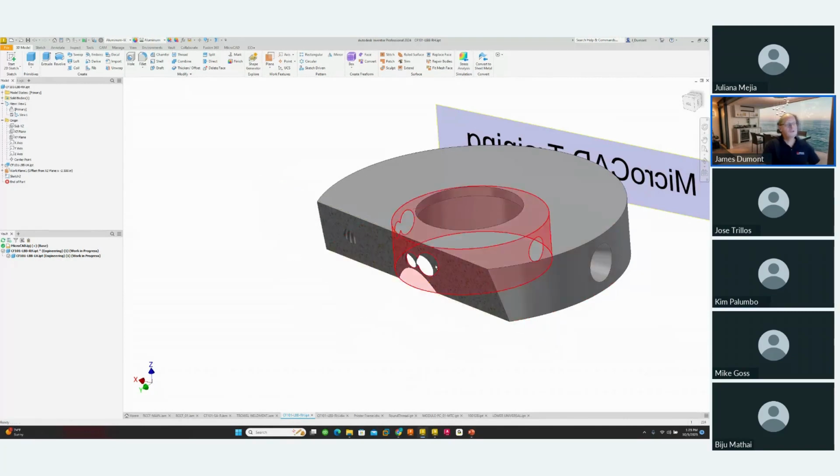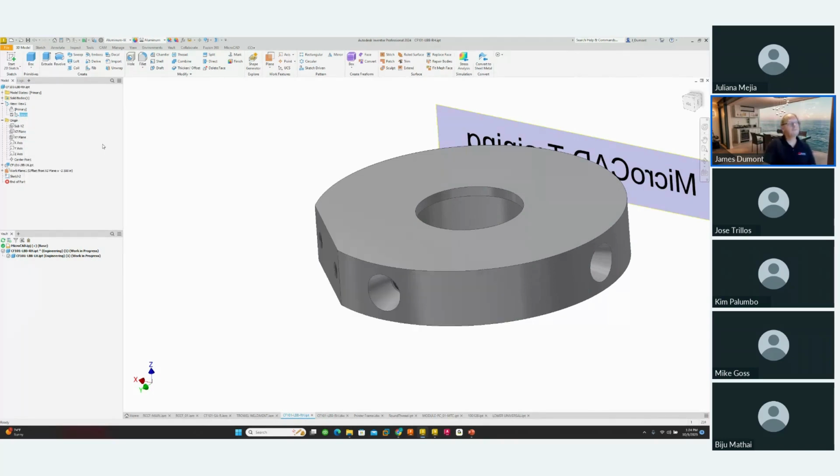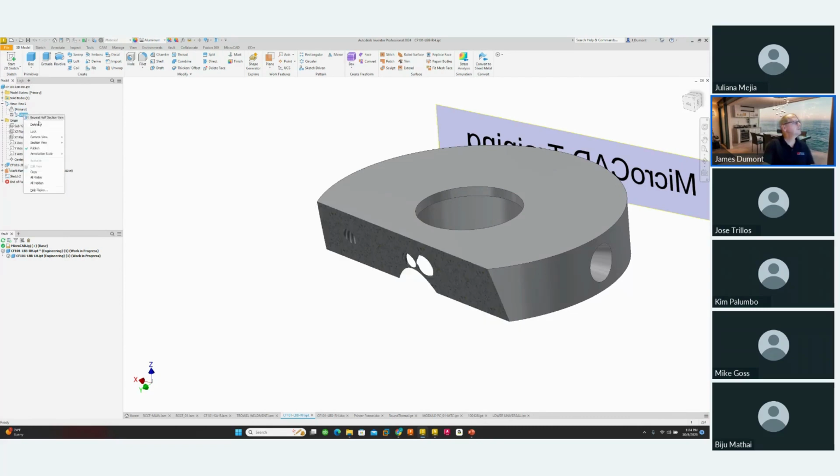Okay. And then once you have it, let's say you wanted to go back and look at it full. A lot of times I create design views for different sections that I'm looking for, half section, 3/4 section, things like that. You can actually go into the section view and suppress it. Instead of switching from the design view, I can just suppress it and then go back, unsuppress it, and edit. So they gave us the ability to edit and suppress the views once we have them. Again, it's all about not having to start over. We have what we want, be able to manipulate it and move on from there.